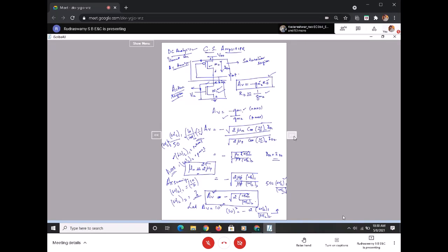Sir, excuse me, sir. Yeah. Sir, should we neglect that negative symbol in that last expression? What is the point in using the negative there? It is always there. But see, that is output with respect to input. Is that clear? If I am giving input to be somewhere like this, what will be my output? Output will be the 180-degree phase shift. There is a phase shift. Here the positive becomes negative, negative becomes positive, but with the amplified version.